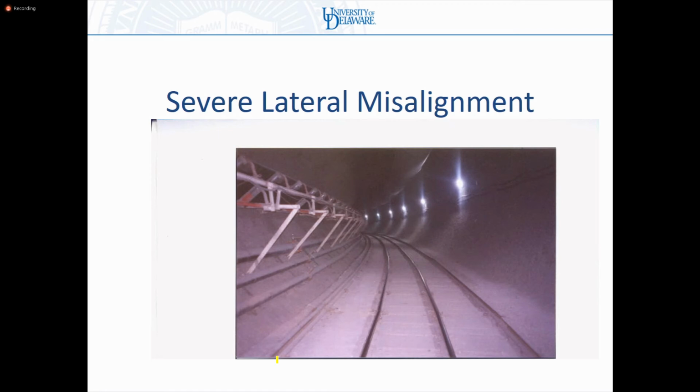If the pour was not uniform and the tolerances of the pour were bad, we've seen summits or dips and peaks and valleys, so to speak, in slab track and tunnels all the time. Whether it's a hump or a dip, whether it goes down or up, depends where your mean is. Most of the time it's down, but you can have a hump as well.